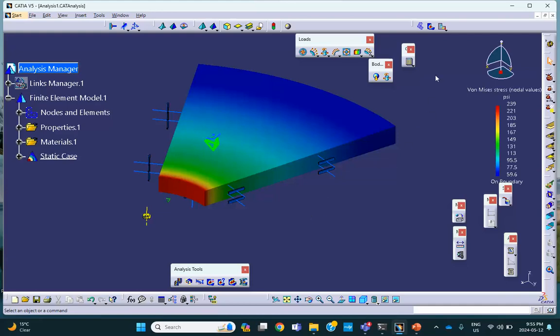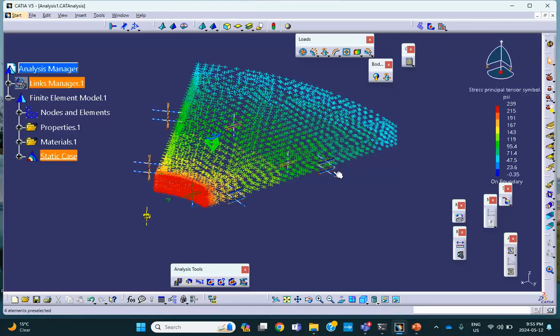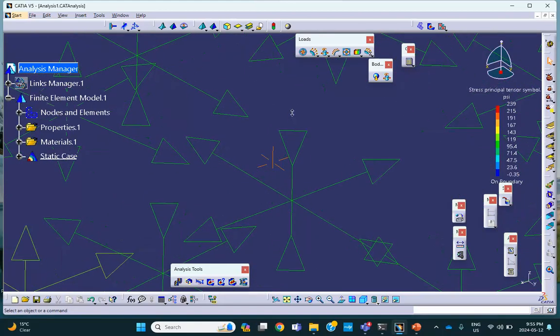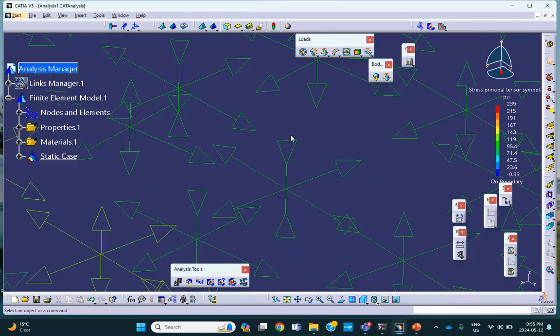The other thing is that if you click on this icon here, see this? This is displacement, right? But it's got other stuff that you can show. Among them, principal stresses. You click on it. Remember from your stress analysis class, you can see that at every point you have three principal directions. The numbers are written here.